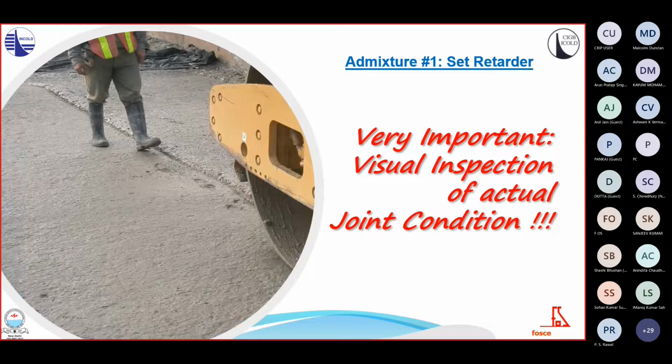However, the actual surface condition of the lift joint must be visually inspected at the placement by experienced supervisors to confirm the test results. The setting time is affected by other parameters, wind, humidity, mix workability, and so on, that are not always well identified in the test.